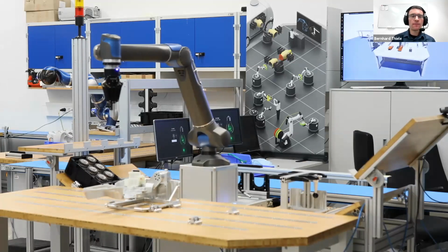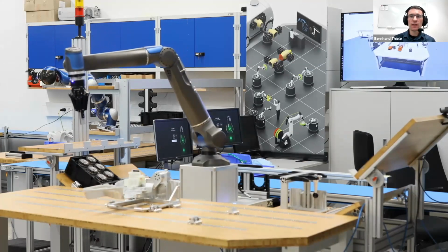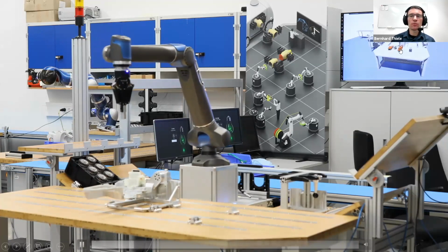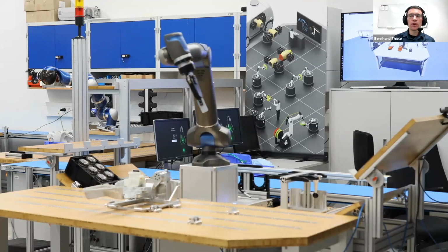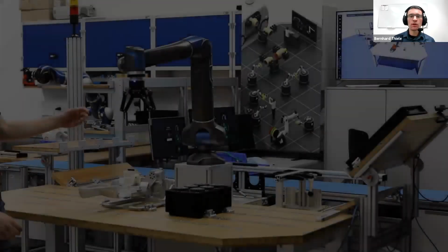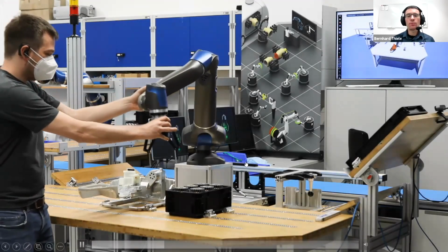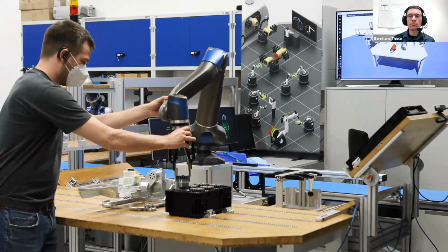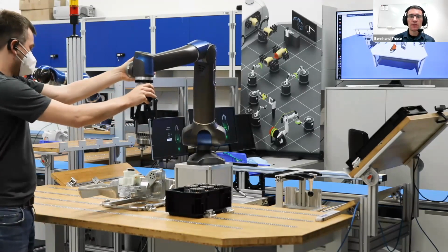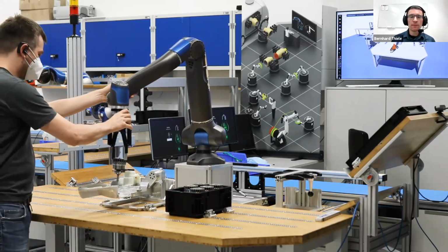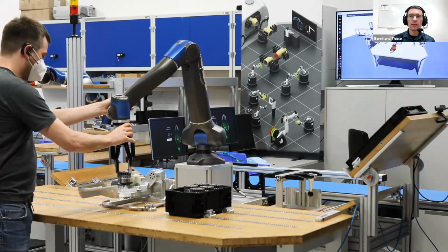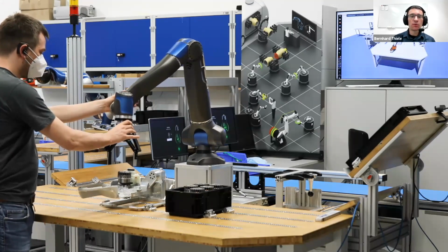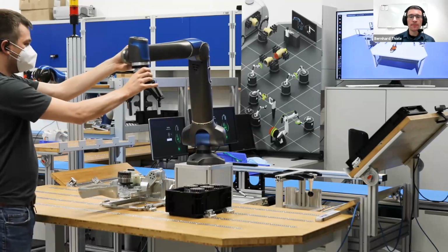Now here we see the robot arm moving, and at the top right corner, you see a visualization of the Modelica model. So the Modelica model is an OPC UA client which connects to the robot, and the robot writes its process data into its OPC UA server, and the Modelica model can access the process data and update its simulation with it. So you see some lag there. Here, the Modelica model then simply mimics what the real robot does.